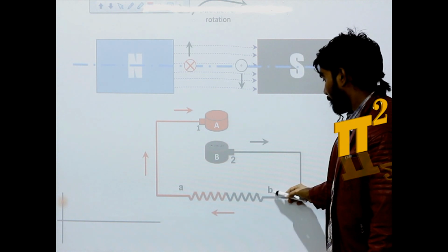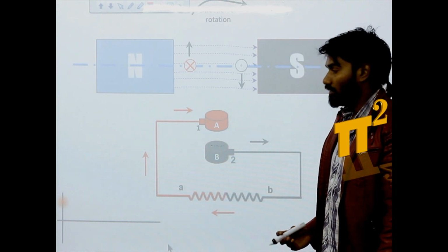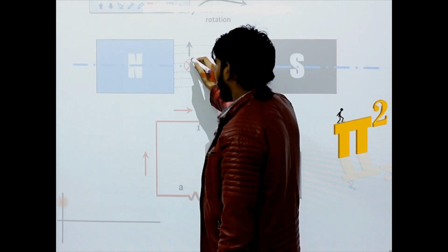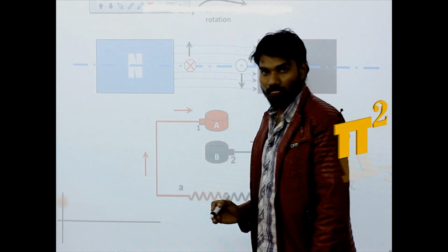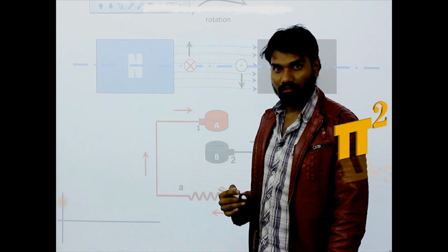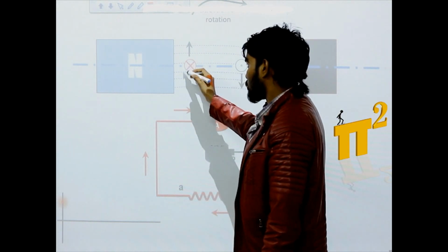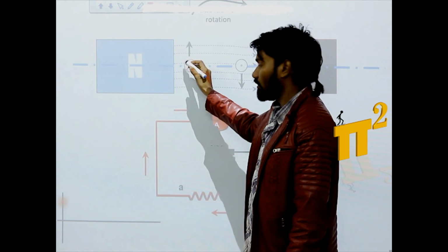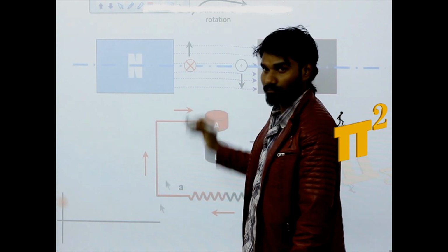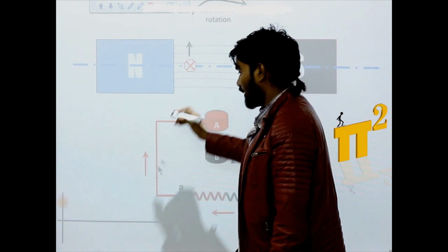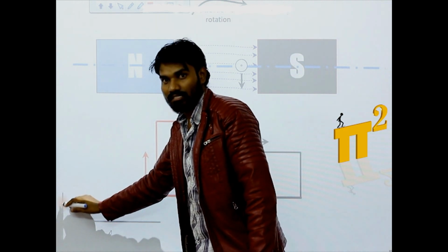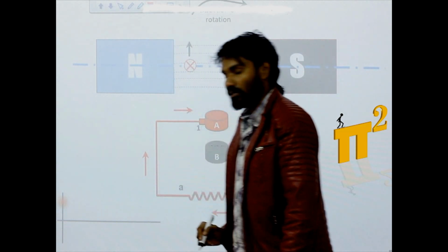So current in the load is from B to A. Now we know force acting at this instant is F, and Fy is equal to F, means the force is maximum only at this instant, and for this maximum here but downwards, here it is upward. As force is maximum, EMF induced will be maximum here. At this rotation, at this instant, EMF induced is maximum.